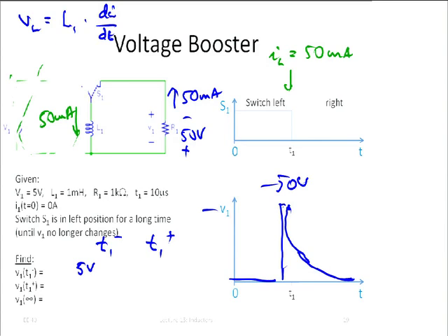So should what be 0? The voltage across the inductor before it's switched. No. Don't do that, right? I've told you that inductors are made out of wire. Resistors are also made out of wire. If you want to make a resistor, you just make a thin and long wire. So you don't replace that wire categorically with a short circuit. Same thing with this inductor. It's an inductor, not a wire. It may be made out of wire, but it behaves differently than an ideal wire.